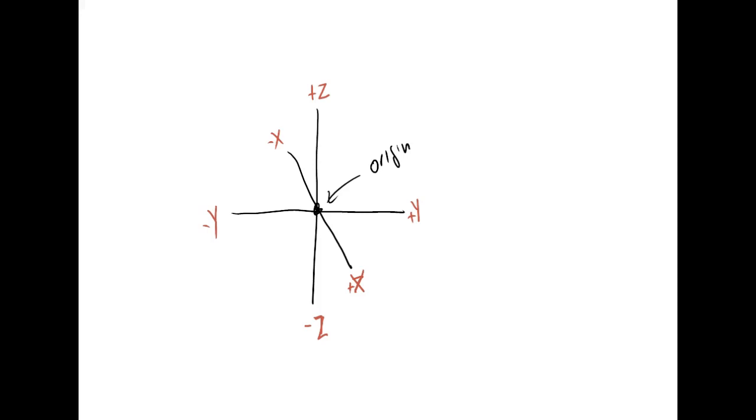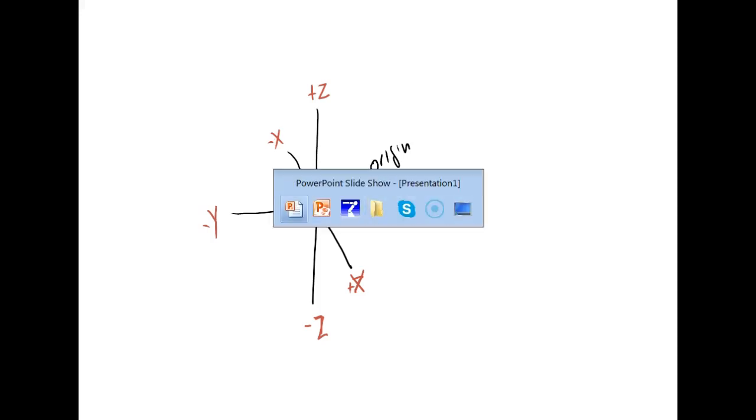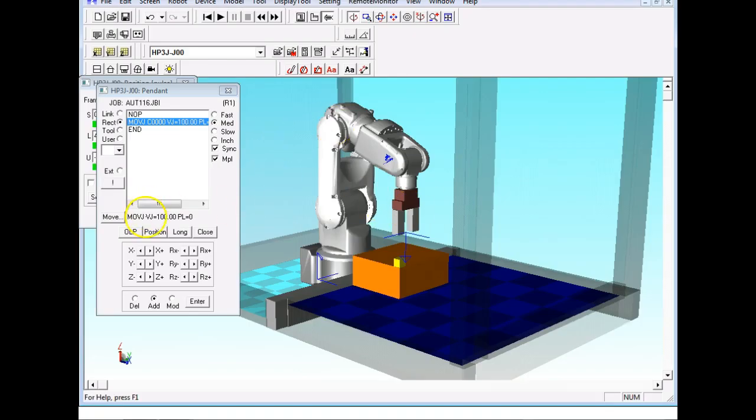And this is a lot easier, so now I'm not saying, okay, do I need to move joint 1? Do I need to move joint 2? Do I need to move joint 3? I say, okay, what I want it to do is I want it to go down. Well, if I want it to go down, I'm going to go to inch. I'm going to go real slow. If I want it to go down, I just, instead of figuring out what joint to move, I move.